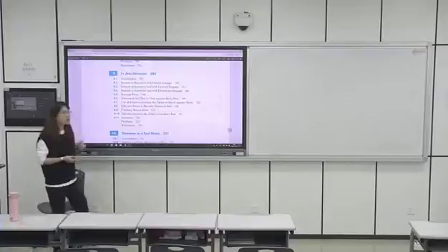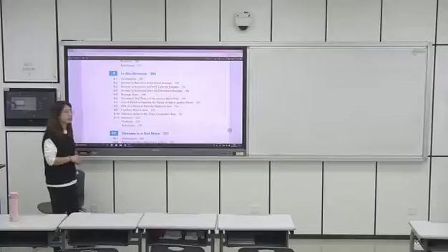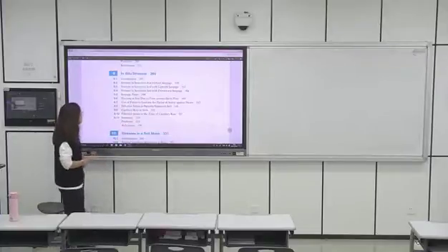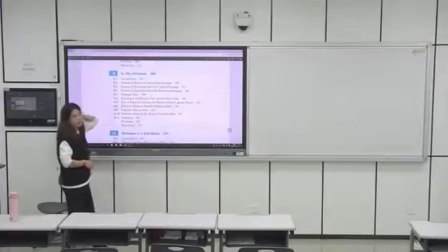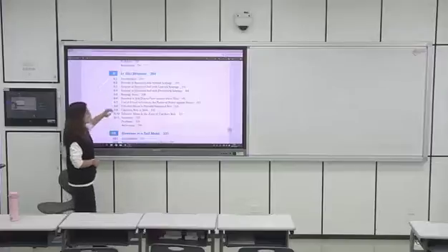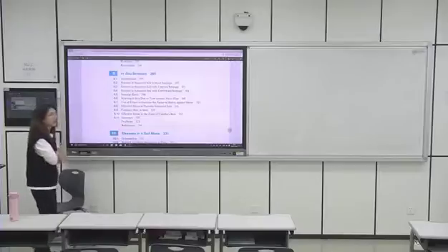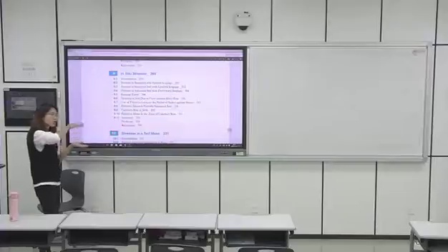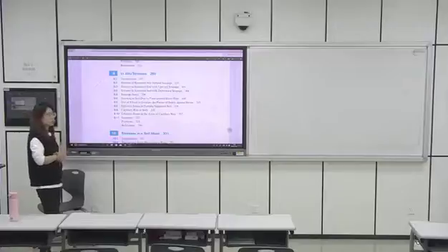Then we need to calculate in situ stress, and maybe later how much load you applied to the soil, right? The total stress, okay? So the in situ stress, we learned 3 different situations. The first is the simplest one, stress in saturated soil without seepage. We said that the stress applied to a soil is the total stress, the overburden stress upon the soil. If the soil is submerged by water, you need to calculate the weight of the soil and also the weight of the water on the soil, right?